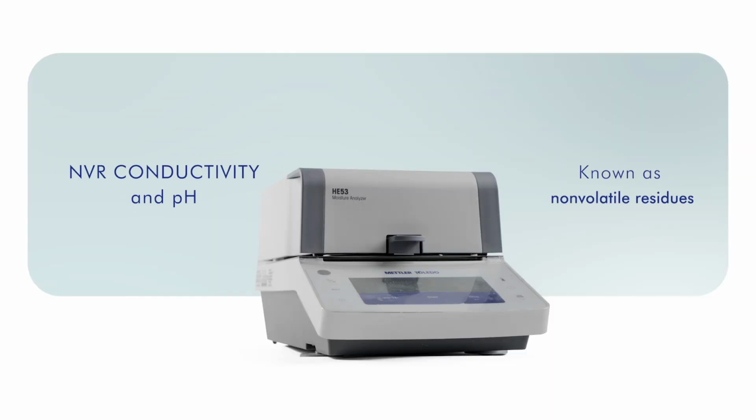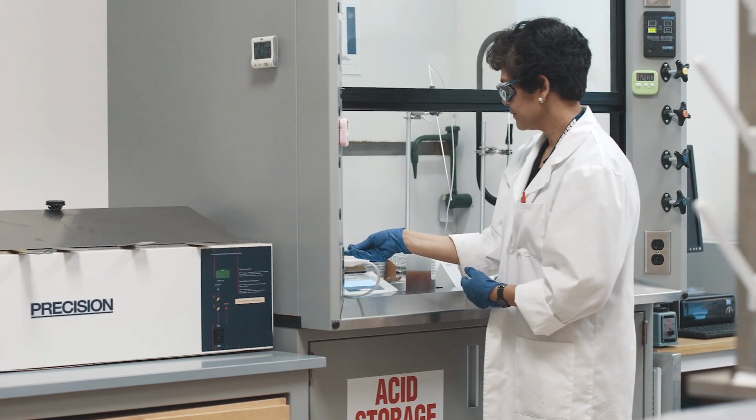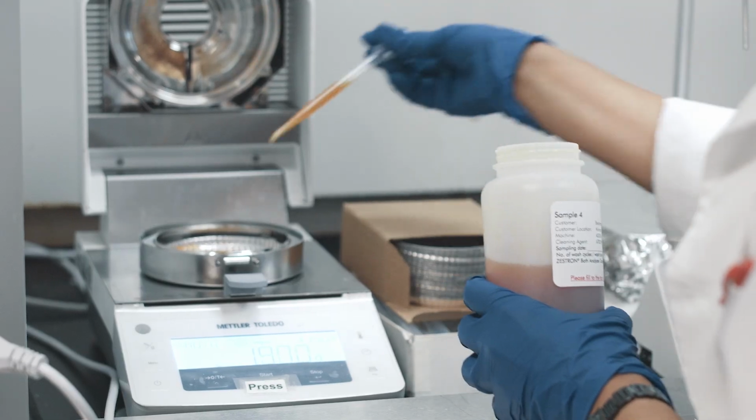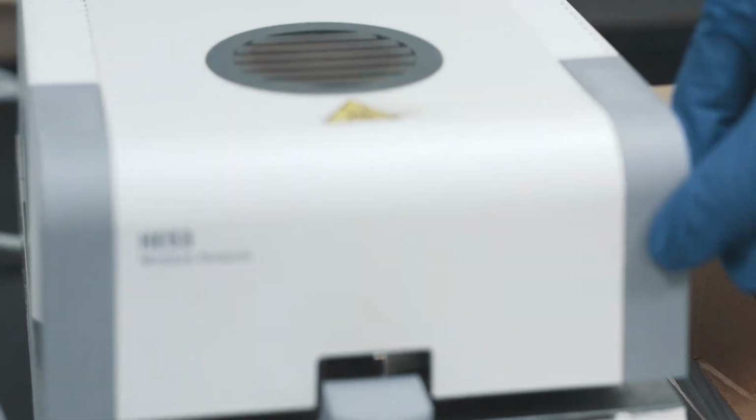The second part of this process monitoring would be NVR, conductivity, and pH. NVR is known as non-volatile residues. These inline and static sensors, however, do not measure the NVR. That takes another piece of analytical test equipment to do so. But essentially, what the NVR is and why it should be of concern: again, for a high reliability process, not only is concentration important, but the NVR is as well.